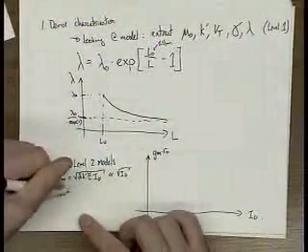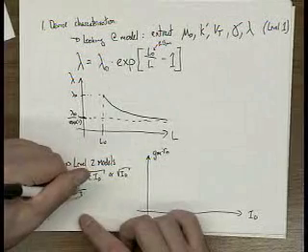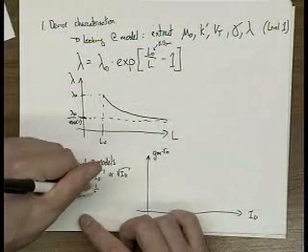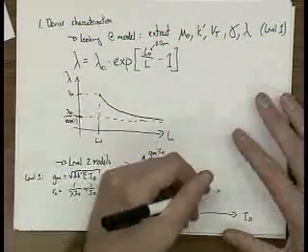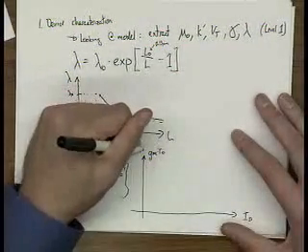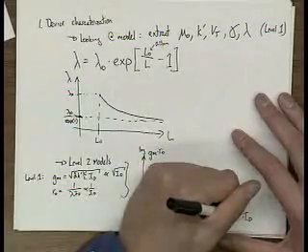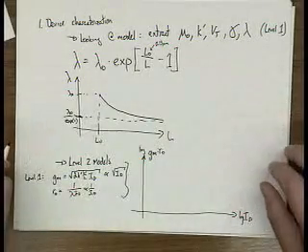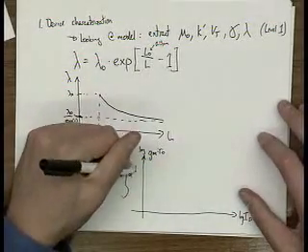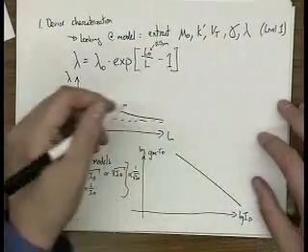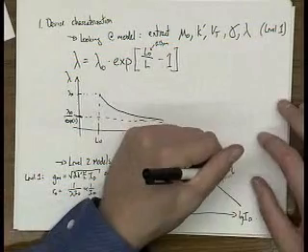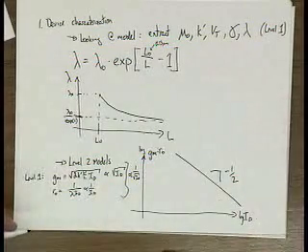R out is equal to 1 over lambda ID, which is proportional to 1 over ID. So that means GM R out of level 1, and I'm going to draw this in a log-log plot so that the square root relationship shows. This is proportional to 1 over root ID, GM R out looks like that with a slope of minus 1/2. Okay?